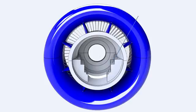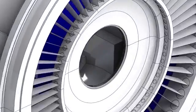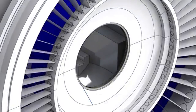The lower half of the bell mouth provides support for bearing number 1. A stationary labyrinth seal is installed at the aft end of the inlet casing to prevent suction of contaminants into the compressor.